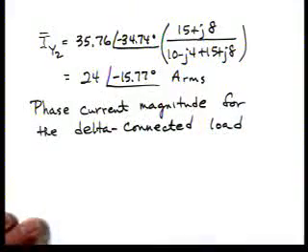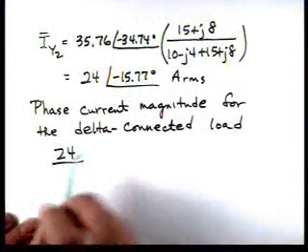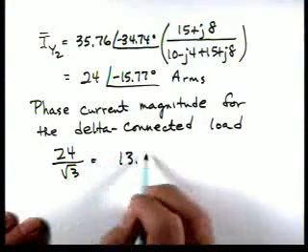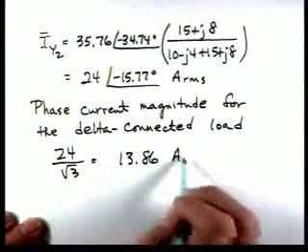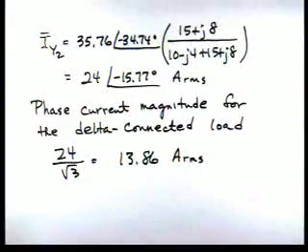If we remember, we take the magnitude of the line current for the delta load and divide it by the square root of 3, and we get the magnitude of the phase current for the delta load. So that's 13.86 amps RMS.